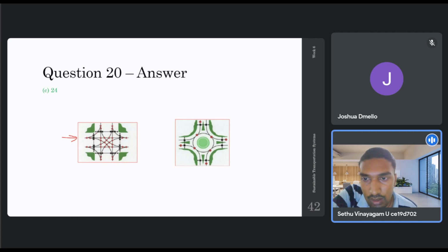And also when they make the turn and try to merge with the through traffic coming from the other side, there will be one conflict happening here. And the turning movement from the westbound approach, when it tries to merge here, will be another conflict. So there are two conflicts from weaving, and two conflicts from merging. This is for one particular approach. Similarly, all the approaches will have a similar number of conflict points from weaving and merging.